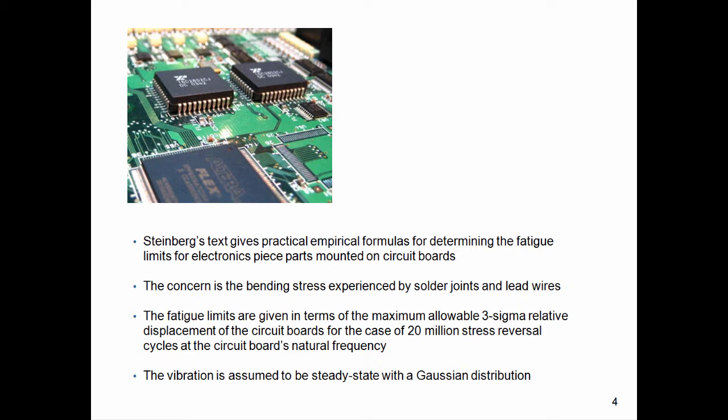But the problem that we're going to come across in our practical engineering applications is that in some cases, at least for a launch vehicle, the number of stress reversal cycles will be far less than 20 million. Maybe a given avionics box only has to survive a matter of minutes during the liftoff and ascent phases of the flight. Or on the other hand, there might be some aircraft or automotive components that may have to withstand more than 20 million stress reversal cycles.